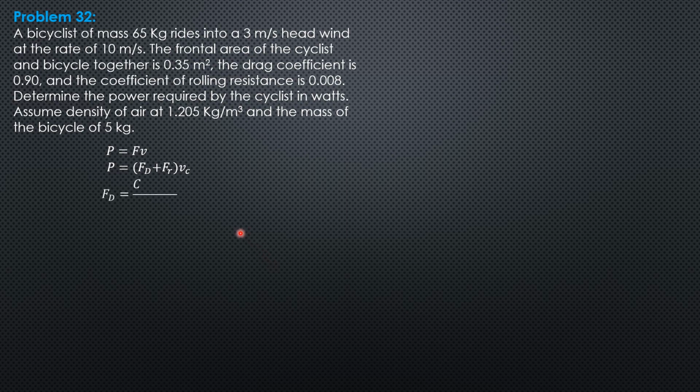So the drag force is coefficient of drag, density, area, velocity squared over 2, where the velocity is equal to 13, 10 plus 3. So substitute 0.9 times 1.205 times projected area 0.35, then quantity 10 plus 3 squared over 2. So the drag force is 32.07 newtons,